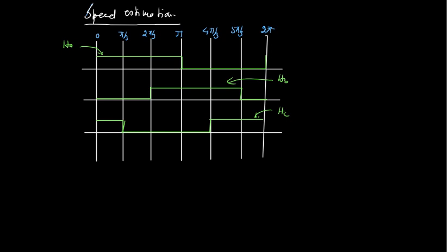Just to avoid any doubt or confusion here, please remember that your back EMF is something like this: 120 degree flat, and then there is a transition, and then it is going like this, 120 degree flat, and then a transition. And likewise for other phases. Okay, this is your back EMF. This is for phase A EMF.